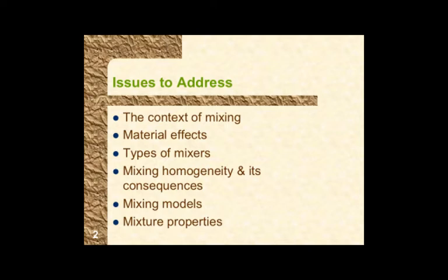If the thermal conductivity is too high and it's a melt and you're putting it into a mold cavity, even if you have good viscosity, what happens to the mixture if the thermal conductivity is too high? It's going to lose heat more rapidly, right? And so maybe it solidifies faster than before completing the whole filling of the mold cavity to create a shape. So you get an imperfect shape, right?